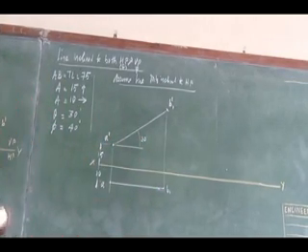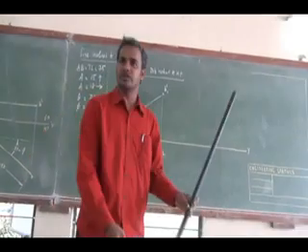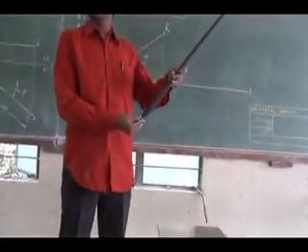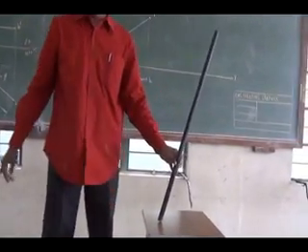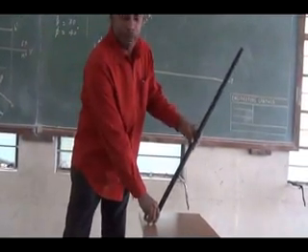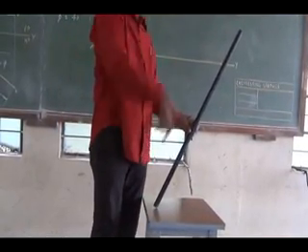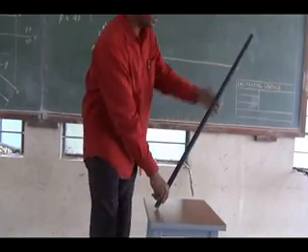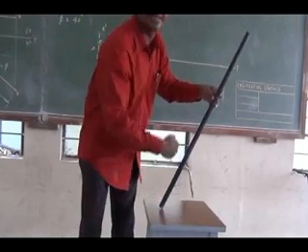You see here in this case, the line is assumed. So instead of the line being some distance above, I am keeping it on the table, and that distance it is above. You see here, it is assumed like this. So actually the line is inclined, which I have assumed, so I have got the projections like this. It is inclined 30 degrees.